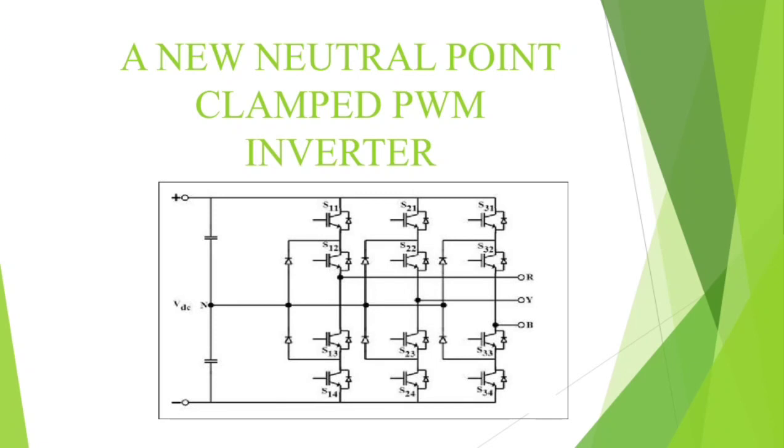Now coming to the working operation of the new neutral point PWM inverter. The basic operation is: when the IGBTs S11, S12 are turned on, the output voltage will be plus VDC. When the IGBTs S12 and S13 are turned on, the output voltage will be 0. Whereas when S13 and S14 are turned on, we get the minus VDC. In this way, we generate the levels of output voltage by using 4 transistors in each leg.